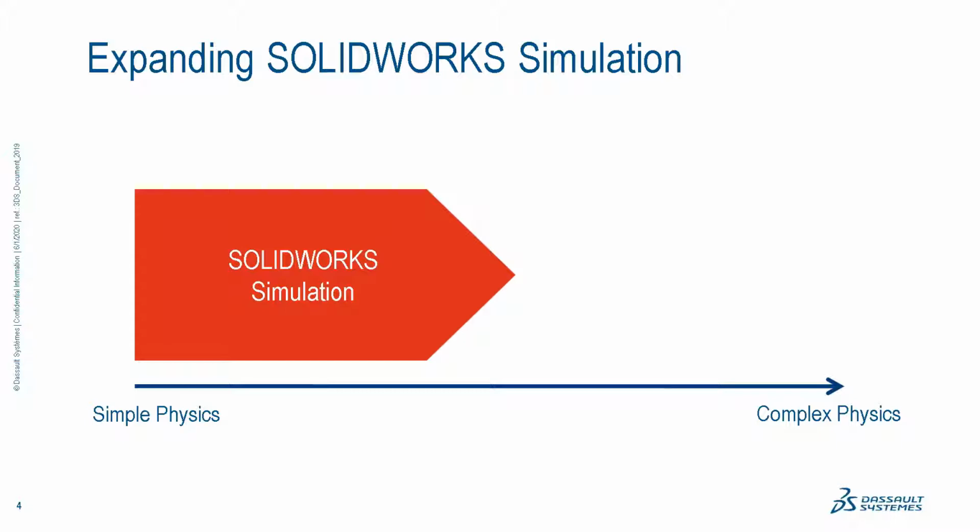But if you're doing really large deformation, large strain, complex material models, models with a lot of contact, often you either can't get a solution, it requires a lot of tweaks to the solver to get a solution, and your runtimes might be really excessive. So it does hit its limits.